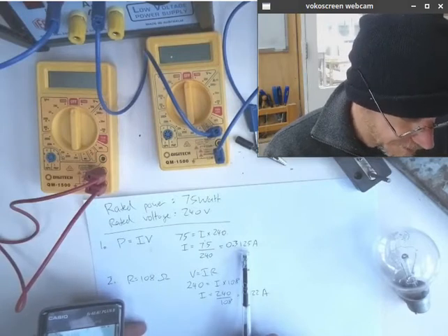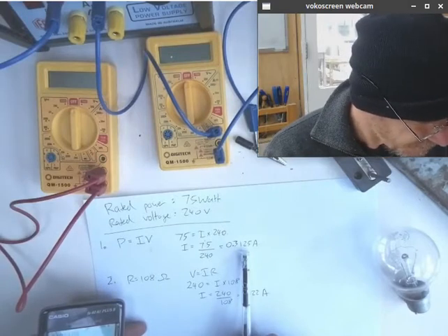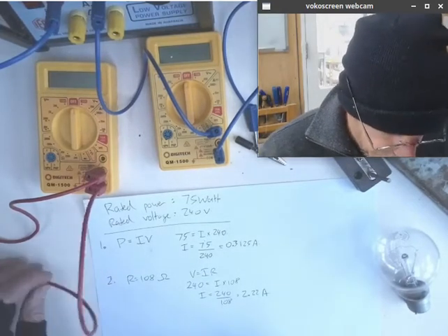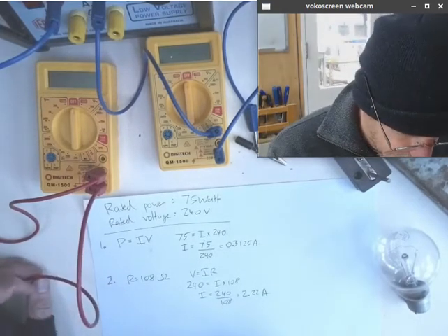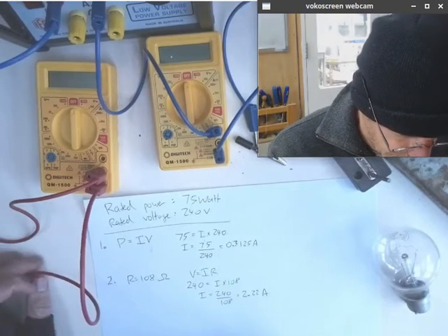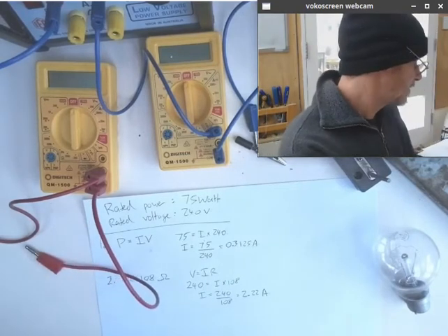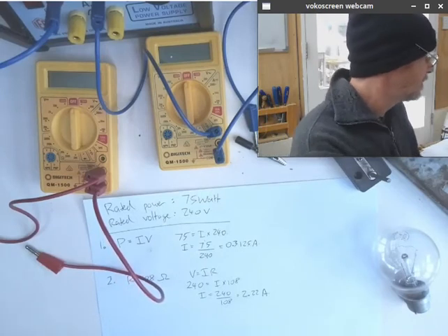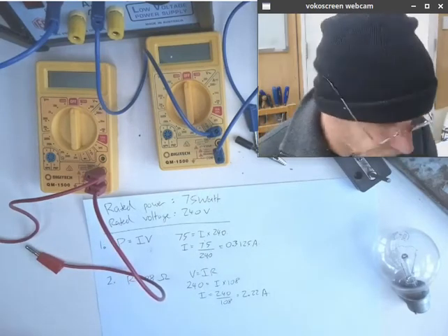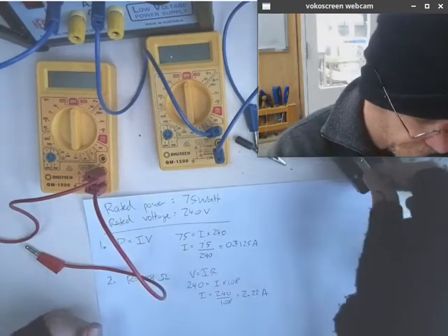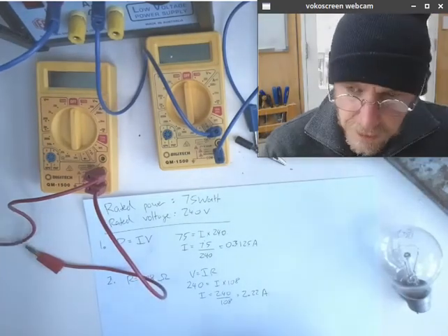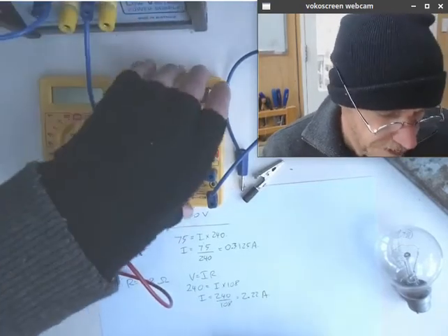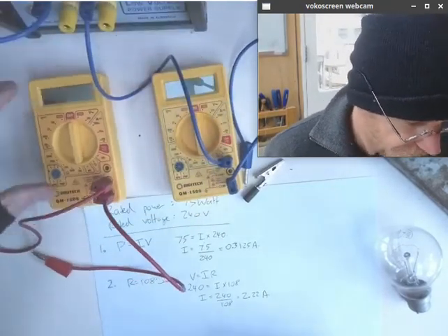which is, as you can see, something like 7 times the current that I got using the rated power. So what's going on? Well, to investigate that, what we're going to do is look at a 12 volt bulb instead, because with a 12 volt bulb I can use this power supply here, and we can take some measurements while it's actually in use as well, safely.